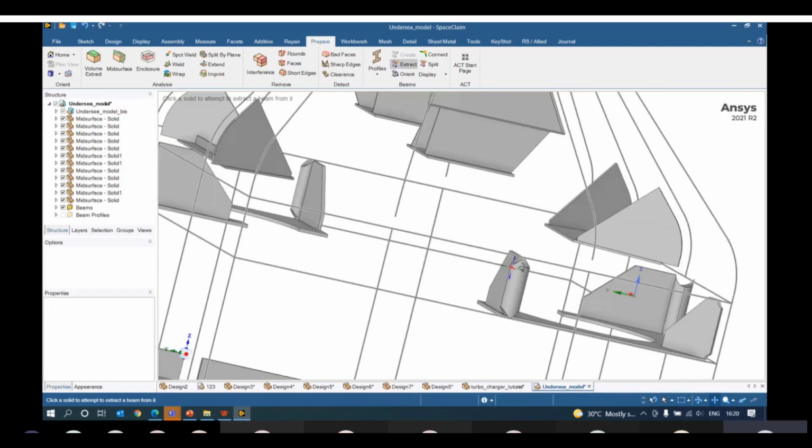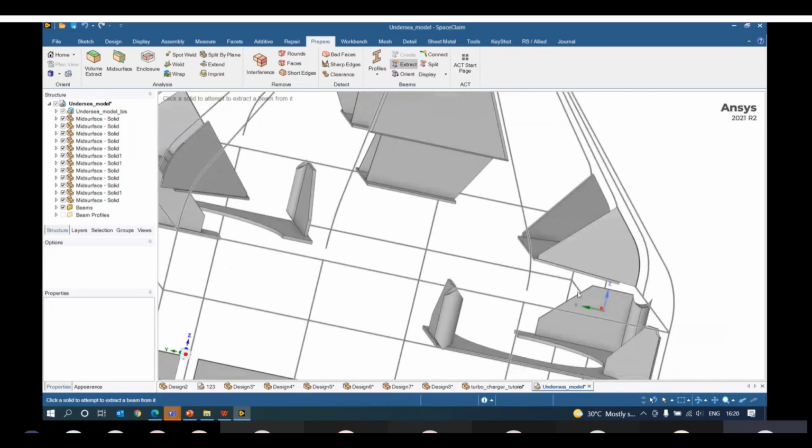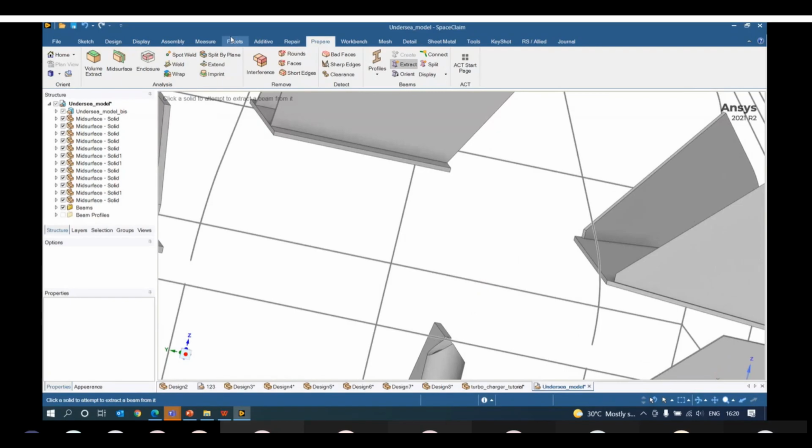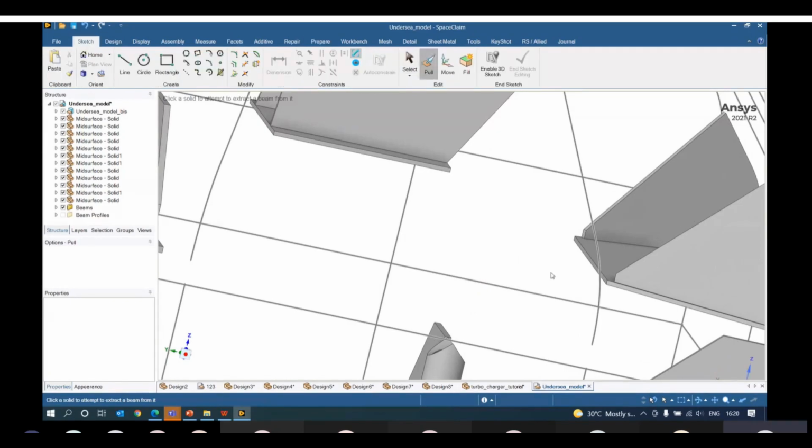For that, you can zoom and you have pull here, select this edge. Now curve one, if you do, then curve extension will create it. You need to take a flat line, whichever is there, and go with up to and select this one so that you are able to convert it. Same way here you can extend, use up to, and this is extended. In this way you have to extend all this.